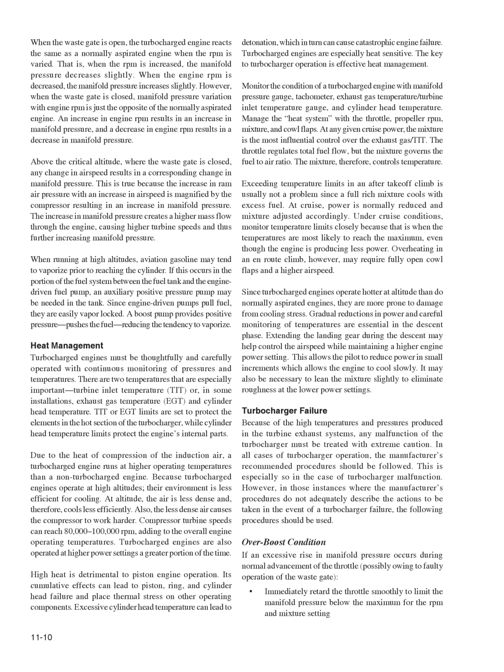Heat management. Turbocharged engines must be thoughtfully and carefully operated with continuous monitoring of pressures and temperatures. There are two temperatures that are especially important: turbine inlet temperature, TIT, or, in some installations, exhaust gas temperature, EGT, and cylinder head temperature. TIT or EGT limits are set to protect the elements in the hot section of the turbocharger, while cylinder head temperature limits protect the engine's internal parts.